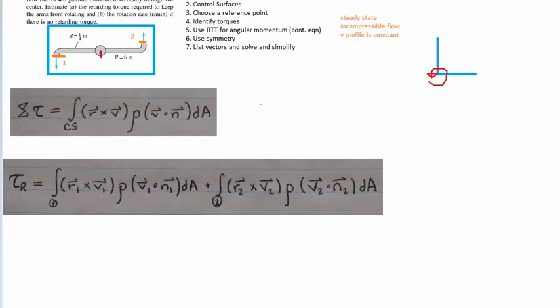Okay, so first thing you should note is that we've chosen our center of symmetry, so our vectors, or our radius arms, need to be relative to that. So for here, if we're going to 1, well, I'll do 2 because it's a little bit easier. It's going to point right like this. I wish they had these arrowheads, but I'll just do it like that. So first it'll point like that, and then since our outlet is right over here, the velocity stream will point like this.